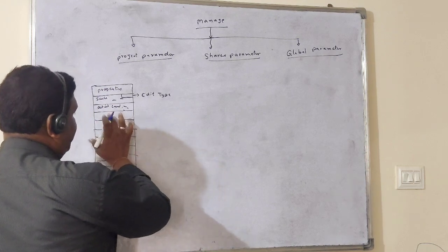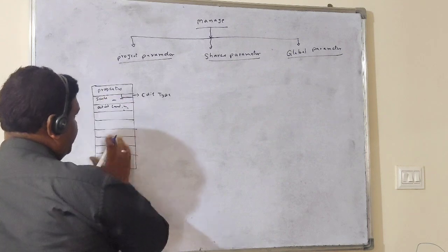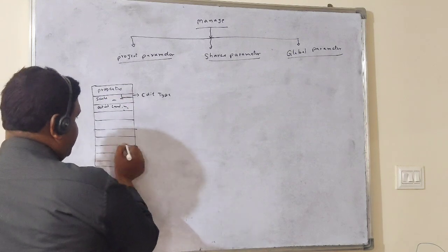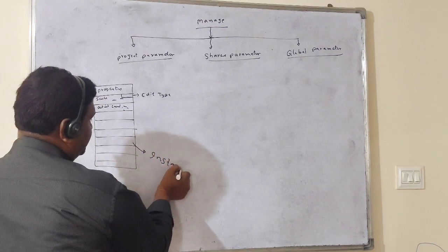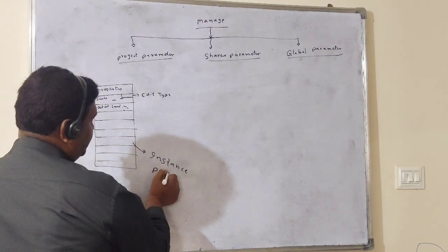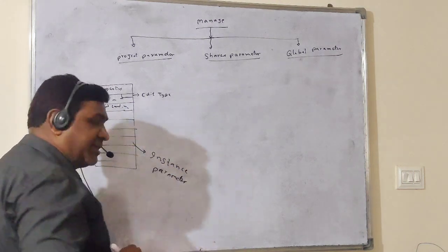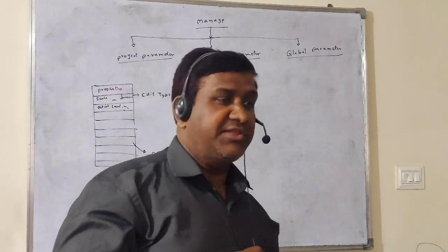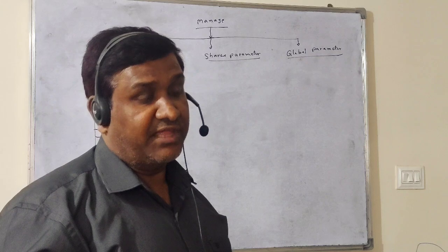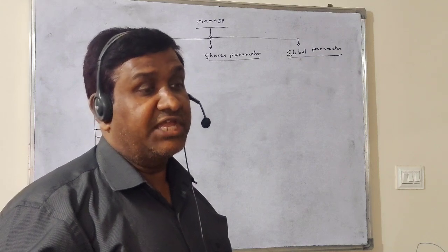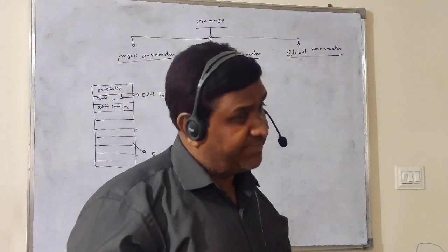Remember, whatever parameters we see directly in the properties toolbar, without going to Edit Type, we call instance parameters. Remember this word, instance parameters. The parameters directly visible in the properties toolbar, that properties information, we call instance parameters. Instance, I-N-S-T-A-N-C-E.